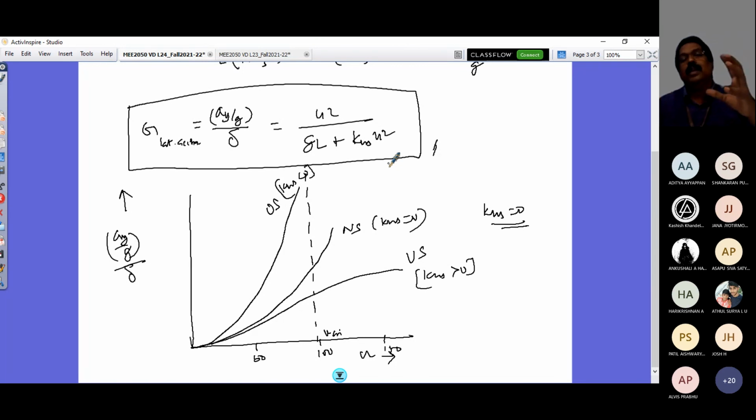So you give your vehicle the input which is coming from the road, and then your vehicle model described by your transfer function, and then you get your output, which is the power spectral density function of acceleration at the target location. So that's what you have seen. Any mathematical model would essentially have the nature of your vehicle, dictated by its transfer function, and the specific steady state motion. If you want to do a comparative study, these steady state gains are the ready metrics to do so.